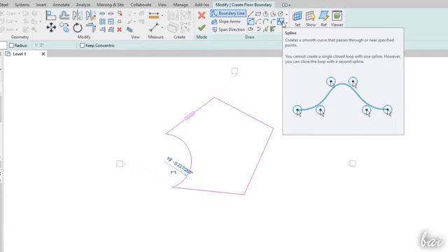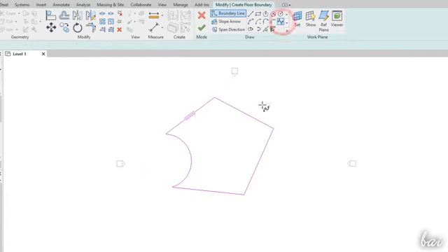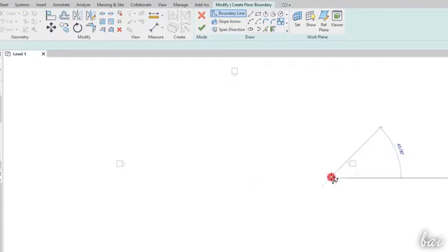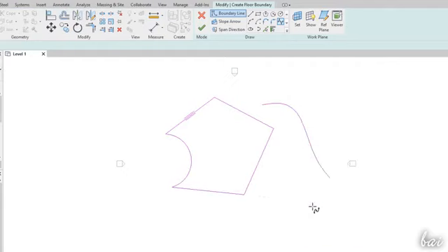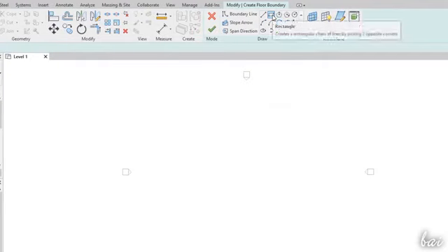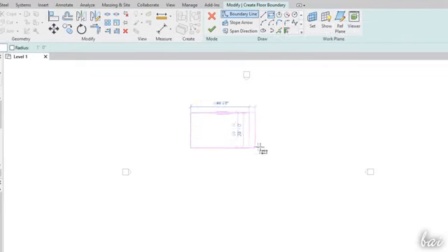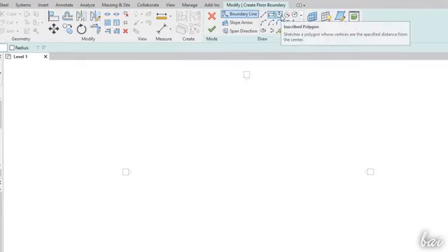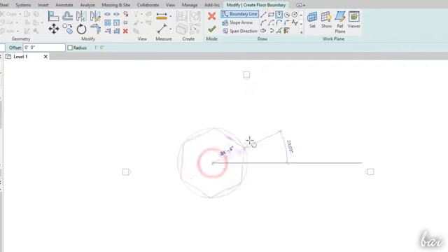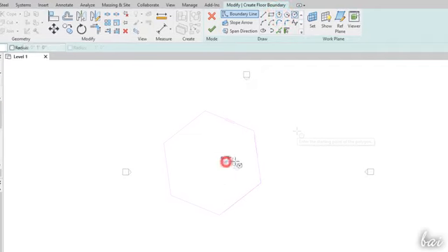In case of lines and spline, you go on dropping consecutive sides as long as you fix points on the workspace, unless you use the Escape key to stop drawing. You can also draw closed regular shapes with the rectangle, the polygon, and the circle tools, fixing the necessary points. You can use the Escape key to undo your drawing in progress.